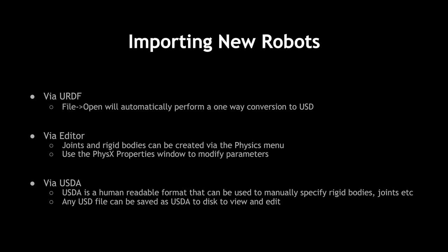Now, there are a couple of caveats with this. The first is that your URDF file is going to be XML, and that XML must be as standard as possible. If you have mistakes, like random, non-terminated items, the import will fail, but you can look at the console when you do the import, and it should tell you some helpful information about where the import failed. From the mesh import side, OBJ files are the best in terms of support, but depending on how you exported your DAE files, those will sometimes work. We recommend that you use OBJ files, though.